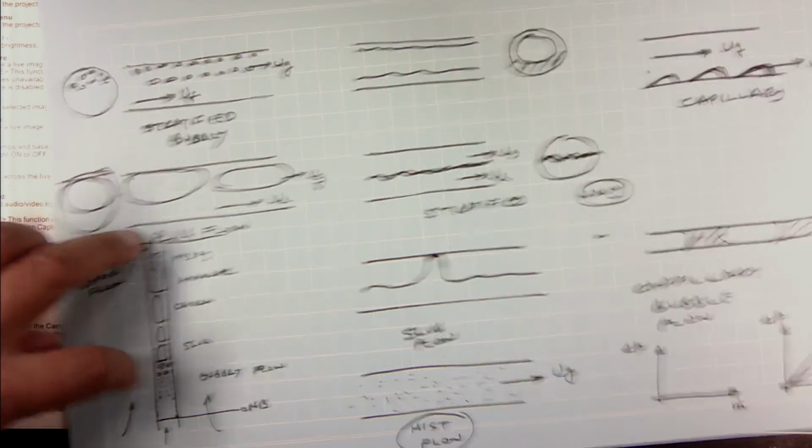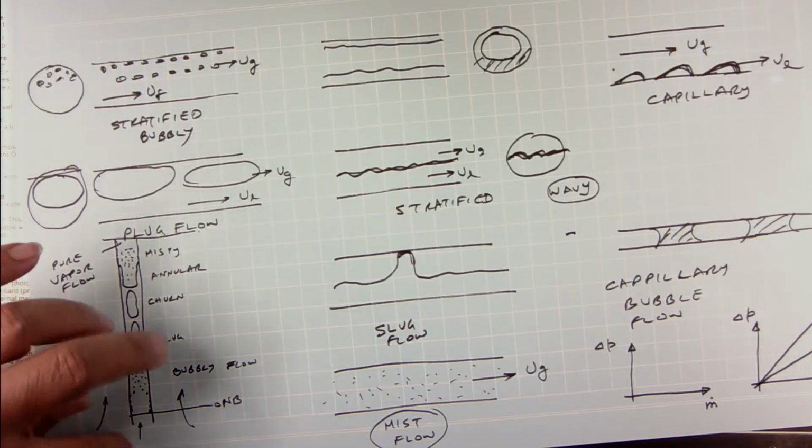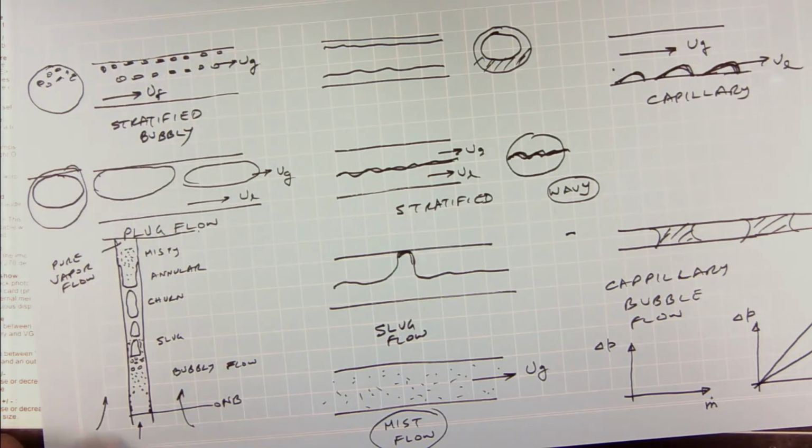So, if I have the properties of vapor, I have the diameter of the tube, I know what the mass flow rate of the liquid is, and so therefore, that should be the mass flow rate of the vapor that is exiting the system. Everything is at 100 degrees Celsius. So, my pure liquid is at 100, my pure vapor is at 100.